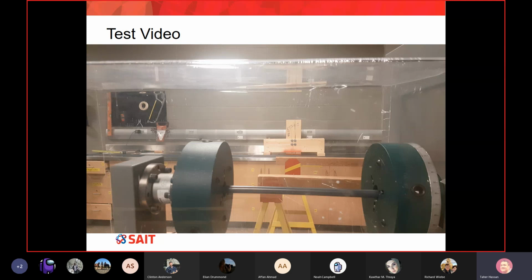Look at the far right side, where my mouse is. I'm asking everyone to look at this. There is a scale here, and this scale tells you the angle of twist. As we apply a torque, remember this head is moving and the left head is not moving. So we're trying to twist our specimen. I will run the test one more time, and please all of you try to look at the far right side of the video.